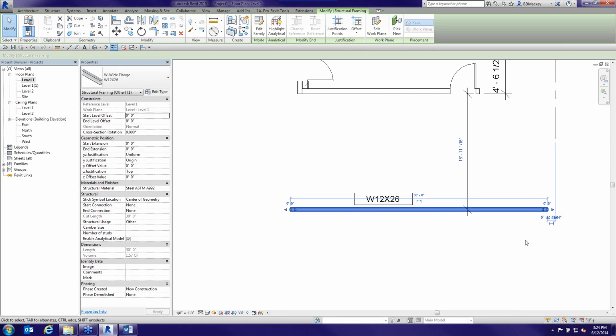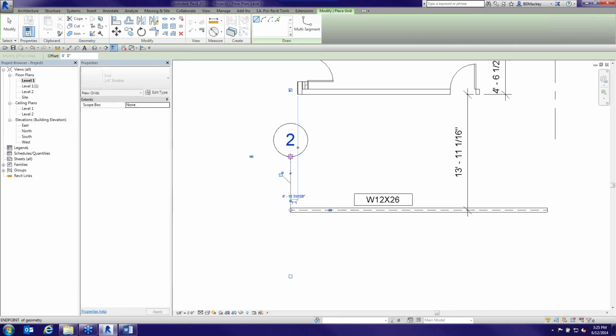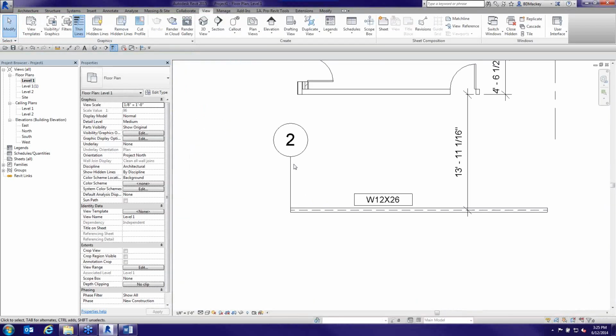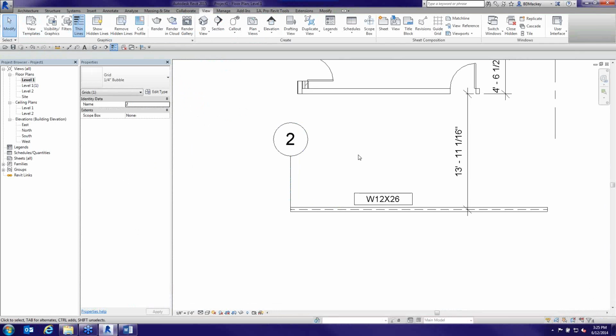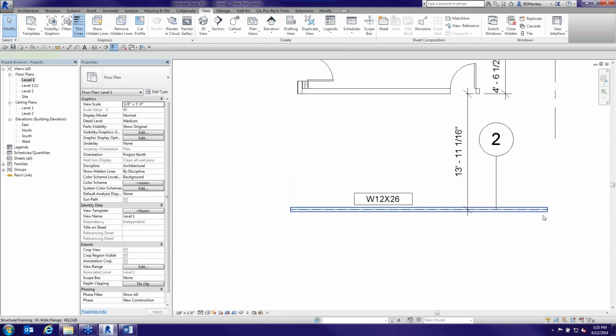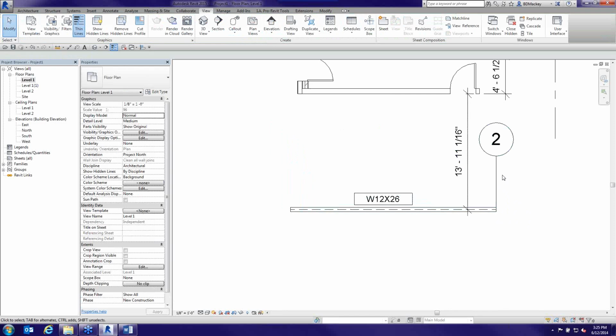This one is huge when I found this, because I'm constantly going, oh, crap, but I wanted it to be 30 feet that way. So the old school way, I came up here and drew a grid or a detail line from this endpoint, and then I took that grid and moved it over 24 feet, since I'm already at 30, right? And then I went to my trim command, or I took the grip and pulled it back to that object. I used to do that a ton when I first started modeling in Revit, because it's how we had to do it in AutoCAD.